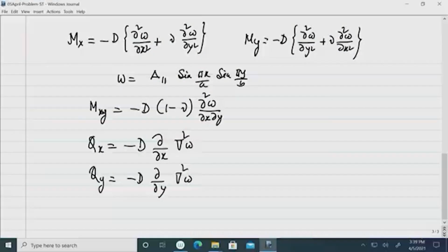Okay. So, what we learned today? Today we have learned the differential equations of bending of a plate subjected to in-plane forces, which we neglected earlier. Now, here we consider the in-plane forces and obtain the differential equations of the plate, and then we discuss the concept of buckling, because this equation will be used in case of buckling also, reversing the sign of these in-plane forces. Then we have solved some problems to illustrate the use of this equation.